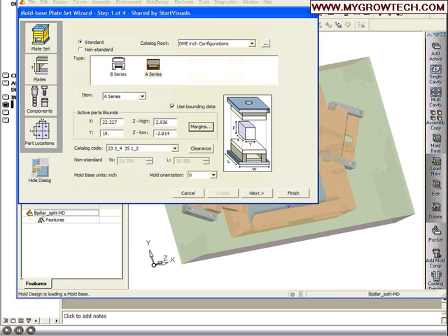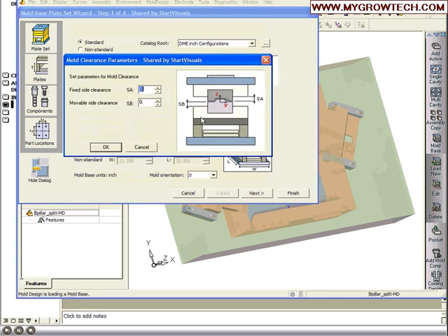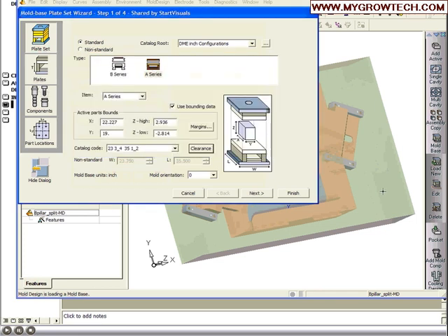It could be that your mold base is going to be maybe nothing more than an ejector box and some components. Say that type of configuration, and then it will size the A and the B plate that you're putting into it if you're doing direct cutting on a non-standard tool. With this, you also can set clearances, and this is describing the preload condition on your inlet, a gap between those retainer plates. Notice when I set my margins, it has sized up in gray what those margins are.